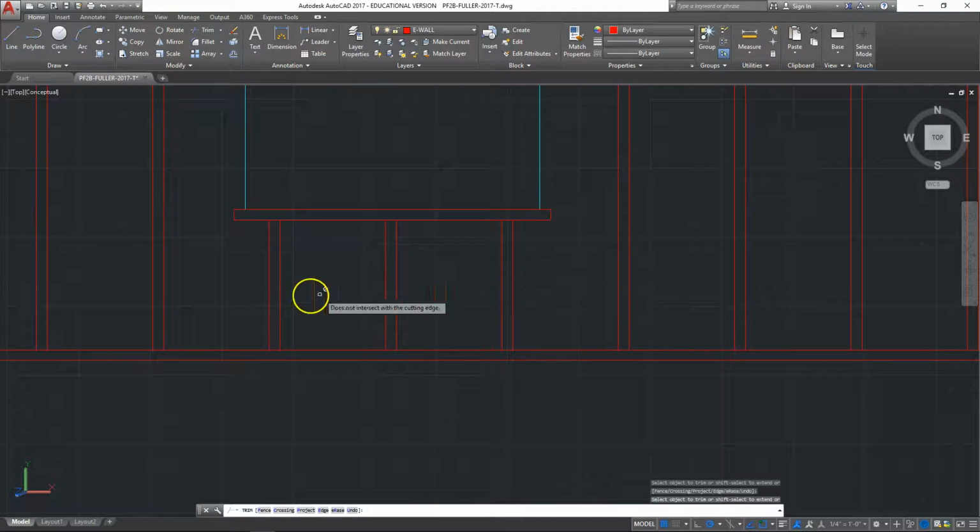The timbers that remain below the sill are also called cripples. Place an additional cripple at each end for additional support.